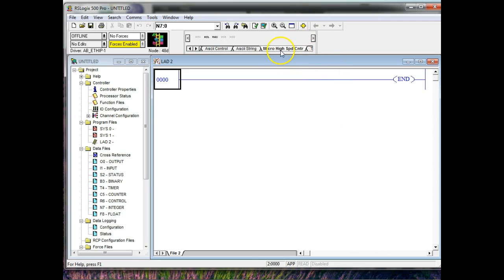And then high-speed counters, which we won't get into this minute. Trig. So this guy, it's got trig, but notice all of them are grayed out, which means what? This CPU doesn't support it. It doesn't mean, if you got it on the 504s, I think the 504 supports all these trig functions. So that's one of the things when you buy a processor, or when you buy a PLC, you need to make sure the version that you get supports the instructions that you need, right? You understand?